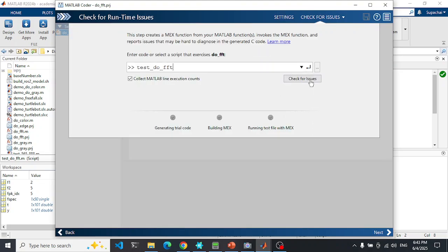The next step here is just to run and see that everything is good. In this one, it will do the code generation into C code, and compile and build into an executable using the internal compiler associated with MATLAB. By the way, this code will be compiled and built for the personal computer, not the hardware that I plan to use today.